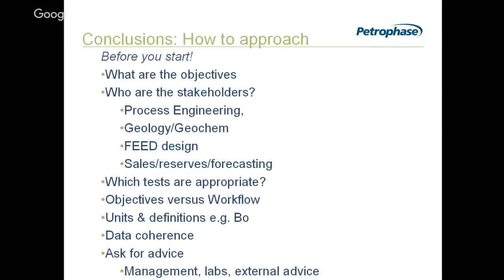You'll get a different value from differential liberation. Why? Because the oil is formed at reservoir temperature, for one thing. You'll get a different answer if it goes through a separator test. You'll get a different answer again if you analyze a bottom hole sample and flash it to atmospheric pressure and say 120 Fahrenheit. Why are they all different? Because they're all flashed at different temperatures. So be careful. Make sure that you're always comparing like with like.